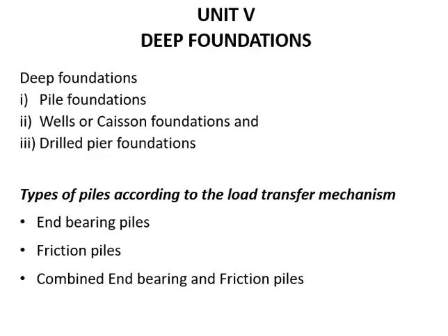Piles are long slender members, either driven or cast in situ. They may be subjected to vertical loads or lateral loads, or sometimes a combination of both vertical and lateral loads. Wells are also called caisson foundations, which are heavier in section and are sunk to the required depth. They are normally used to carry very heavy loads, such as the loads from bridge piers or multi-storied buildings.